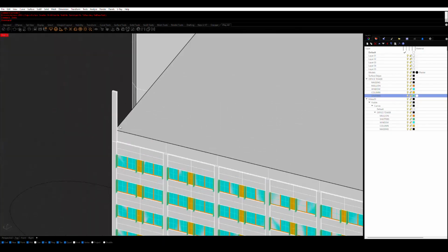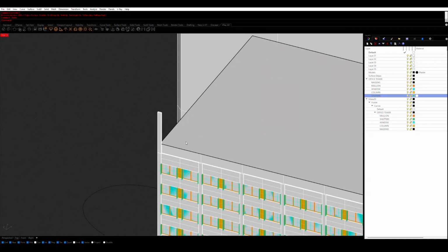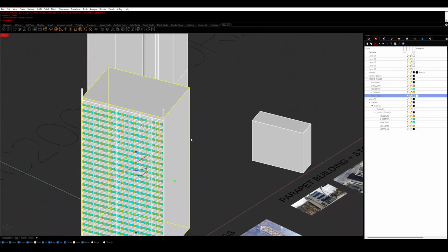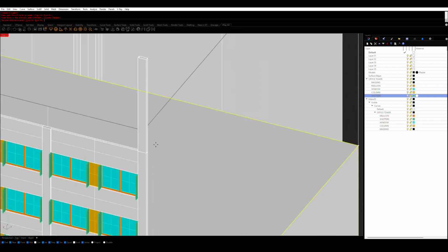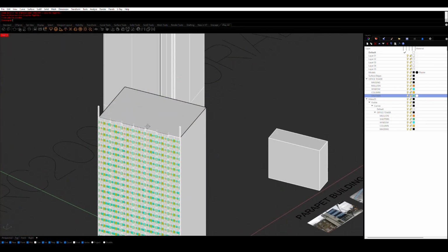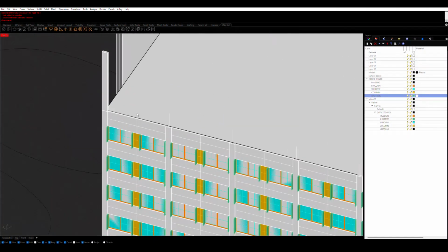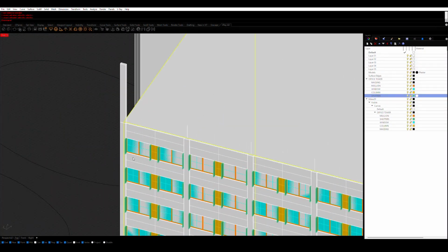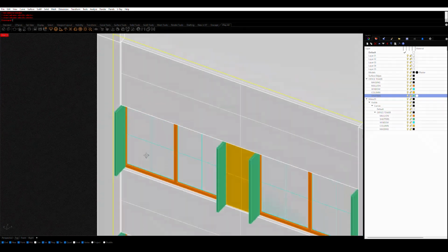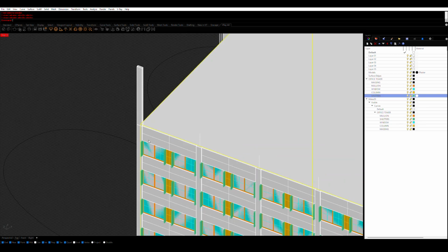Okay. And from here, we'll also lower this to that level, the initial massing. And once you have all four sides of the massing cladded, there's essentially no need to keep it around, especially because it overlaps with our windows, and that might cause some problems when making 2D.